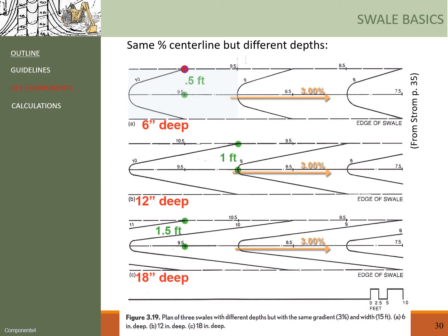And if you look at the location of spot A, that is the spot at the 10 feet elevation on the edge, it is exactly at the half contour spacing from the spot that's at 10 feet elevation on the center line. I know that is a mouthful, but you get the idea. And why is that? So in terms of elevation, A and A1 should be the same, right? Because they're both at the 10-foot elevation. And if the elevation difference between spot A and spot B is 0.5 feet, that's the depth of the swell, right? Then the difference between A1 and B is also half a foot, which means the horizontal distance between A1 and B is 0.5 contour spacing. Does that make sense?